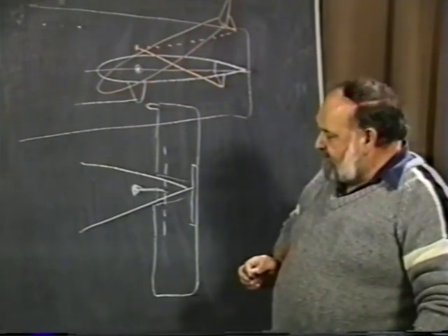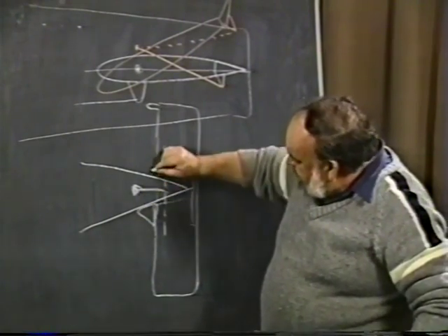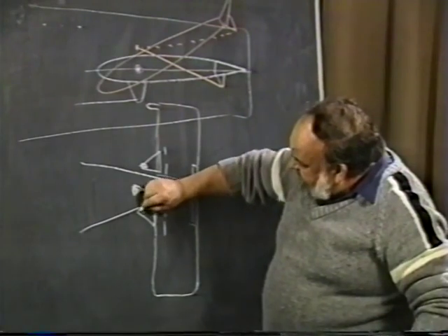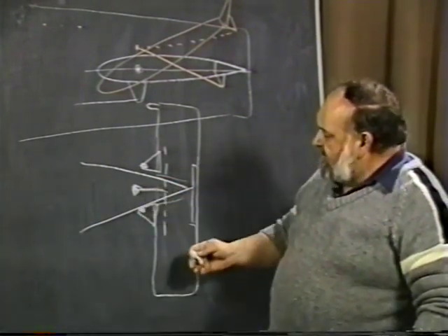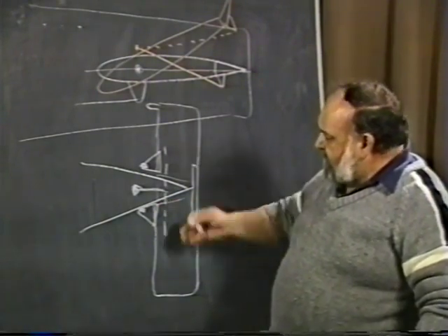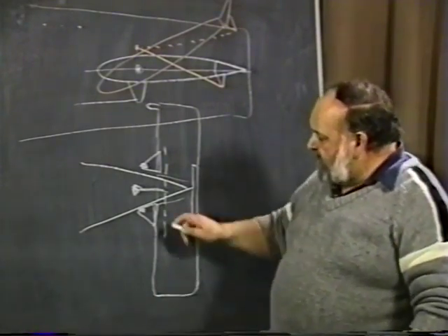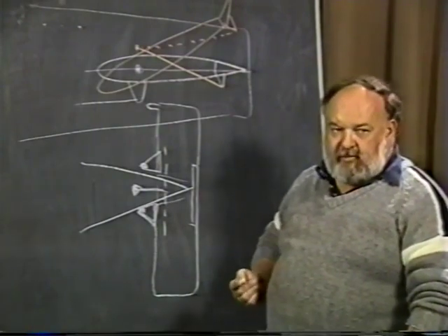One of the ways we came up with it, though, is why not build little surfaces out here like this and put the lead on that. Now this did two things. One, it got us the lead further out from the leading edge. It put some on both surfaces so it balanced the thing so that it was torsionally pretty nice and stable. But most important, it gave us that aerodynamic characteristic of a little delta wing or swept wing surface in here.